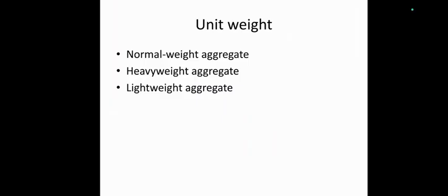What type of aggregate based on the texture is preferred? Crystalline aggregate, because crystalline will have a rough texture, so better interlocking will happen when compared to other textures. In glassy aggregate, the bonding won't happen between the cement paste and the aggregate. If it is honeycomb and porous, it will absorb all the water which is used for making the concrete and the hydration process. So preferably we should go for crystalline aggregate. Smooth also won't have proper interlocking.